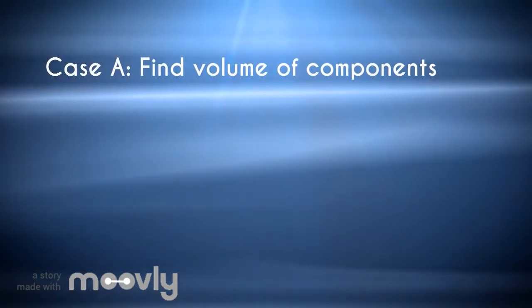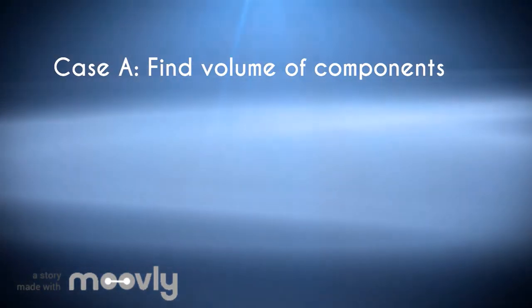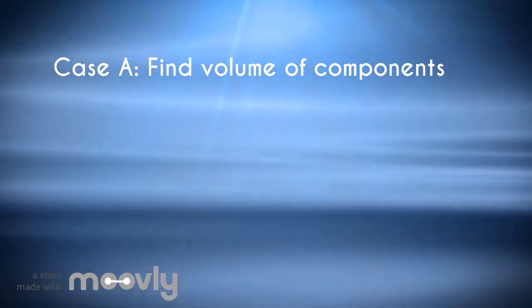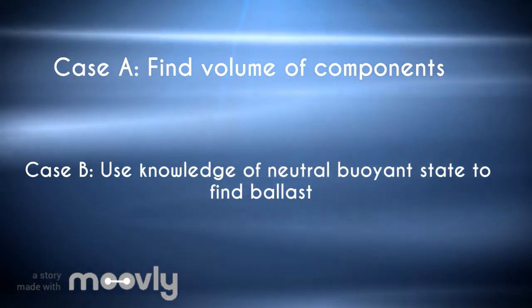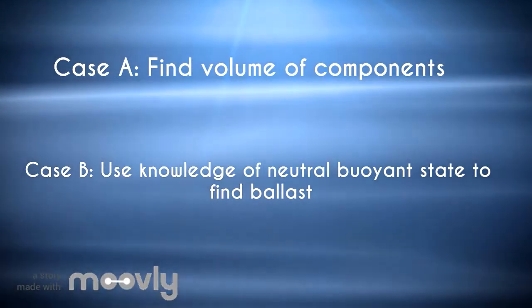There are two different methods we can use to find the ballast weight. In case A, we use our knowledge of the volume of the components to calculate the weight required versus the actual weight of each component to find the ballast weight. In case B, we use our knowledge of the behavior of a neutrally buoyant object to figure out the ballast weight through observation. The steps for case A are as follows.